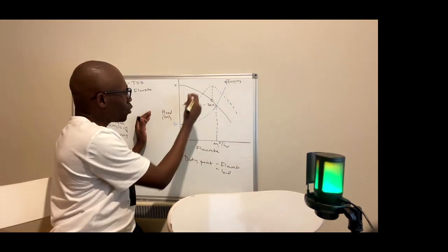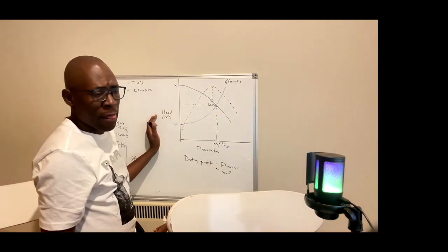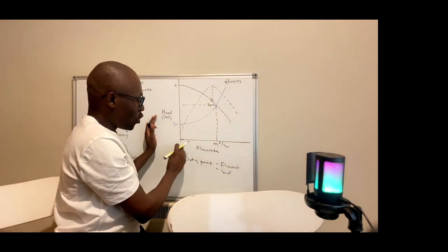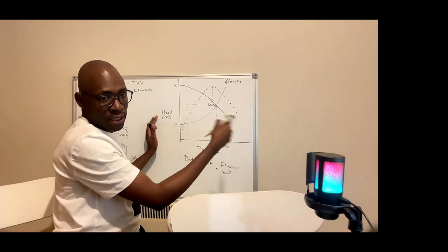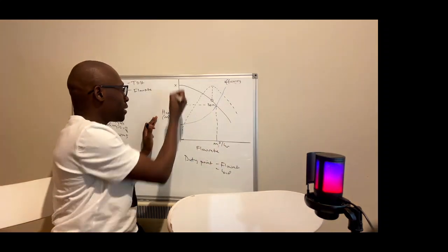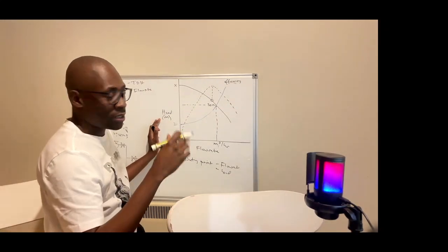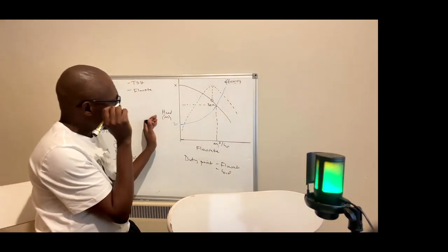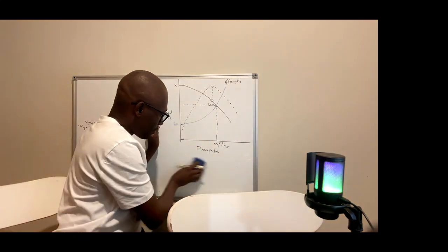So let's look at this curve. That's a pump curve. The first thing that I'll show you is that on the x-axis you have your flow rate, whether it's cubic meters per hour or liters per second. Then on the vertical y-axis you have your head, whether it's head in meters or feet, it doesn't really matter. Then the next thing that you have is what is called a pump curve.